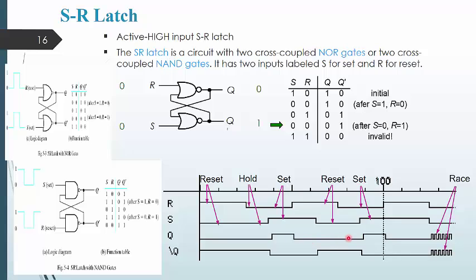And this is what we can get implemented or we can get described over here with the help of these waveforms. But you can see the condition that when both R and S are 1 at the simultaneous instance. So here neither Q nor Q bar will be high in that situation. Rather than that, here we will see the continuous transition of both Q and Q bar outputs.